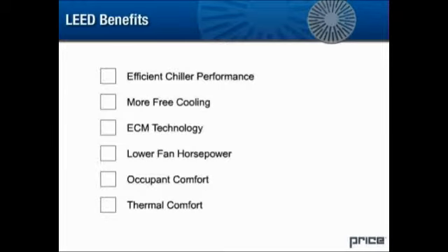To summarize, underfloor air distribution provides many benefits, such as a more efficient chiller performance, more free cooling, ECM technology, lower fan horsepower, occupant comfort, and thermal comfort for reducing energy consumption and earning valuable LEED points.